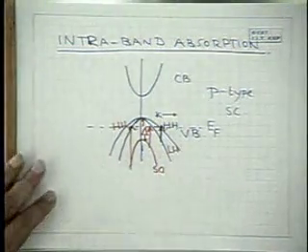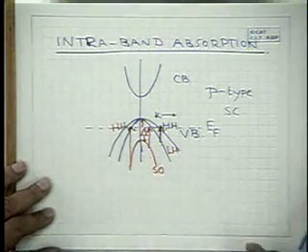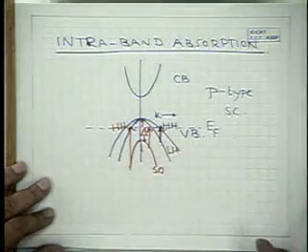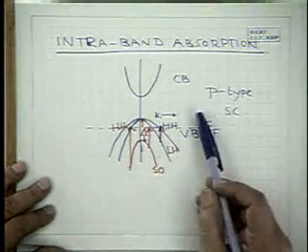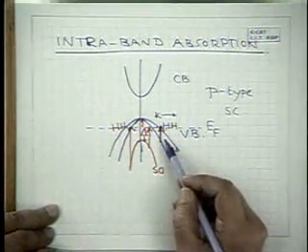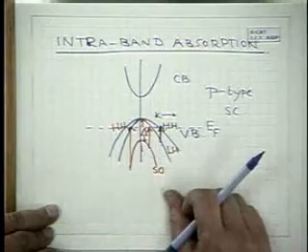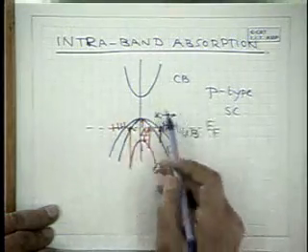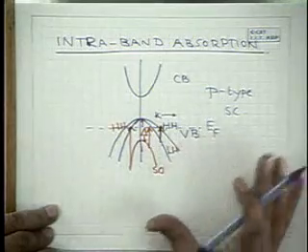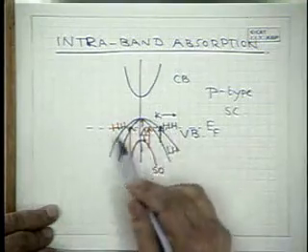This is important sometimes in heavily doped p-type materials, and sometimes this is undesirable, and we want to reduce the optical absorption due to intraband absorption. And one of the ways, as we'll see in the case of lasers, is that we can alter the band structure by having strained layers. We can change this band structure if we apply either compressional or tensile stress, and thereby reduce this sort of spurious optical absorption.